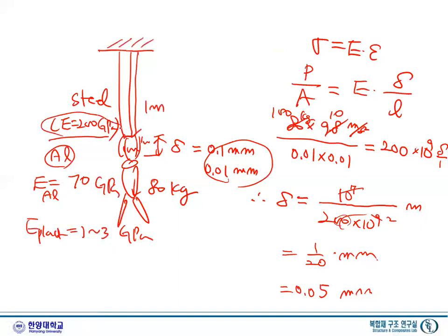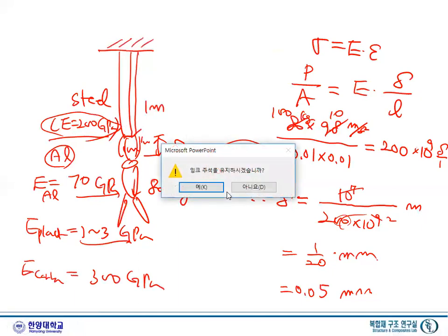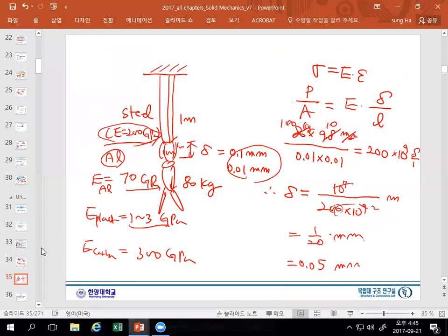And you can see that 200 is kind of a reference, and you can easily understand how soft or how stiff. Carbon fiber, very stiff, will be 300 gigapascal, which is even stiffer than steel. Okay? So anyhow, I recommend you remember this 200 gigapascal. Okay. Now, next one.